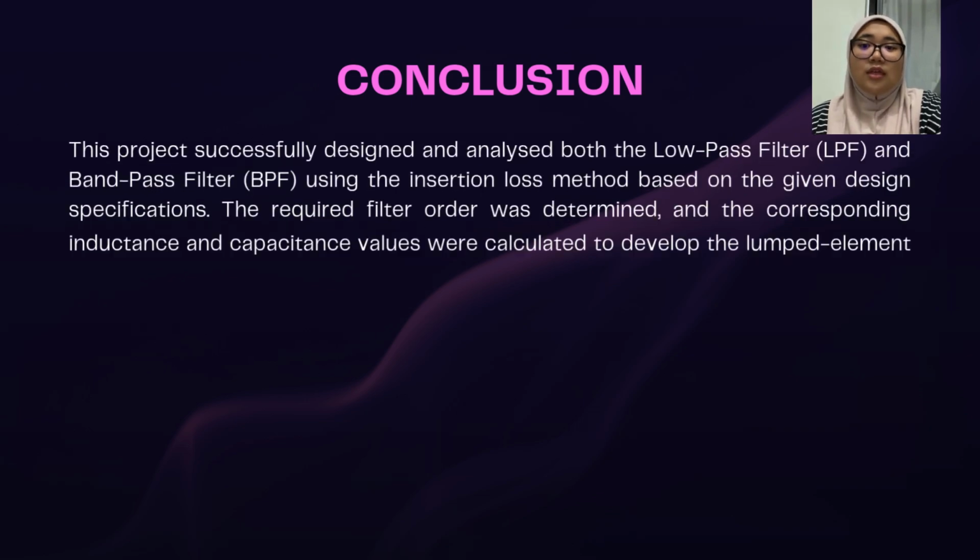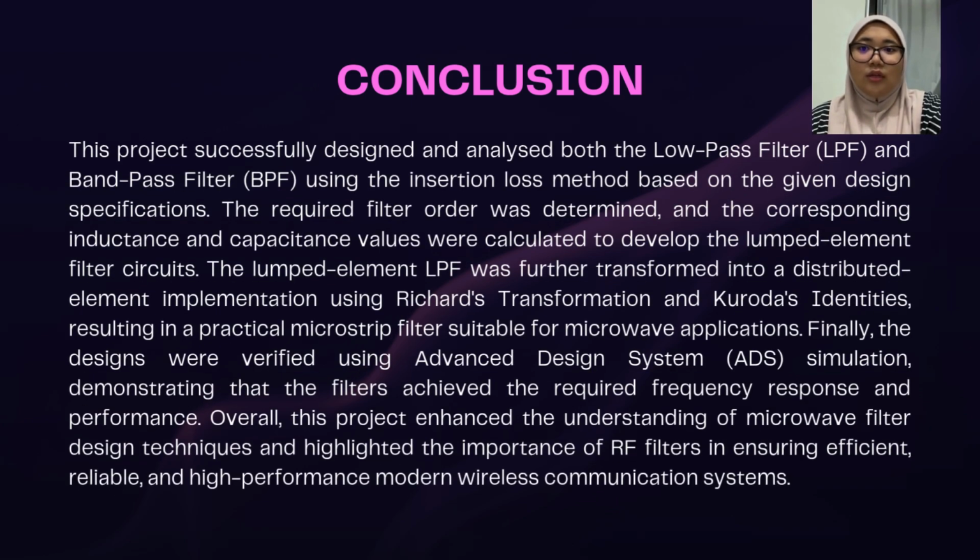IoT devices. In conclusion, this project successfully designed and analyzed both the low-pass filter and bandpass filter using the insertion loss method. The lumped element low-pass filter was transformed into a distributed microstrip implementation using Richards transformation and Kuroda's identities. ADS simulation confirmed that both filters achieved the required frequency response and performance. This project enhanced our understanding of RF filter design and demonstrated the importance of RF filters in modern wireless communication systems.